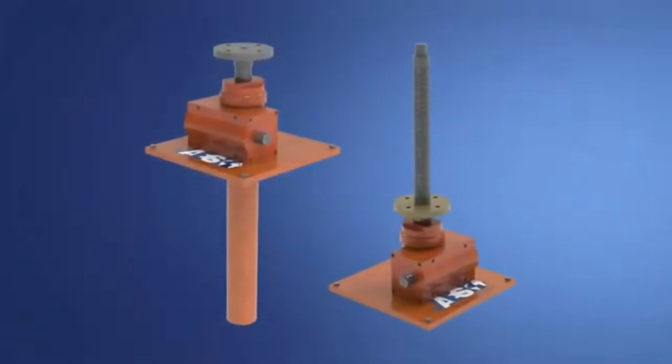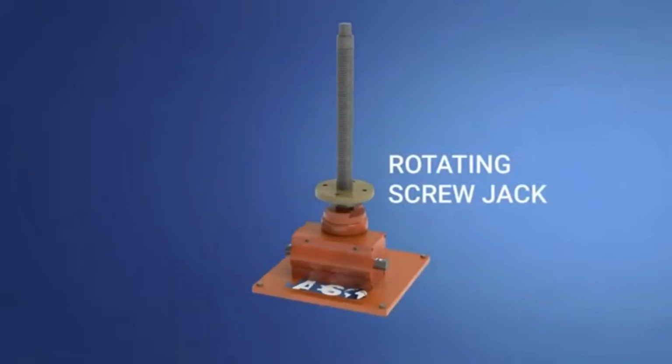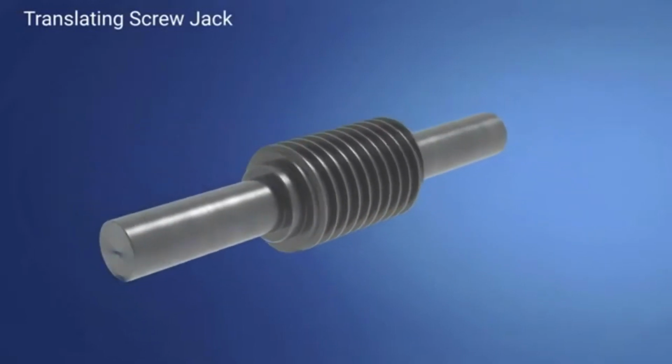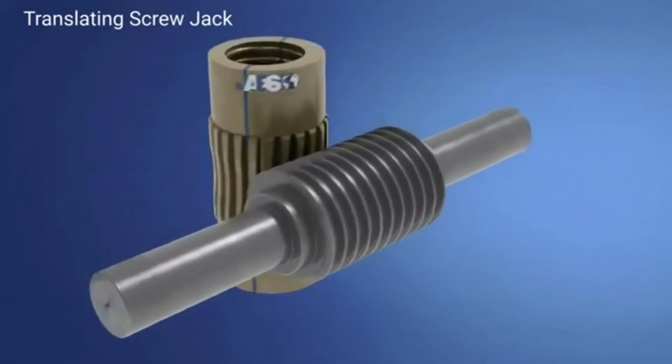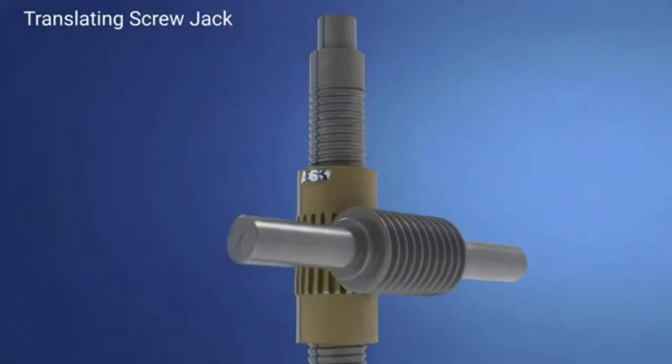There are two types of screw jacks: the translating screw jack and the rotating screw jack. The translating screw jacks are the most commonly specified jacks. With this design, a driven worm acts on an internal worm gear, which in turn drives a lead screw.